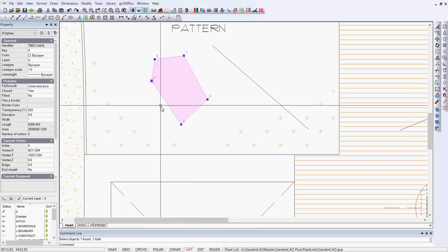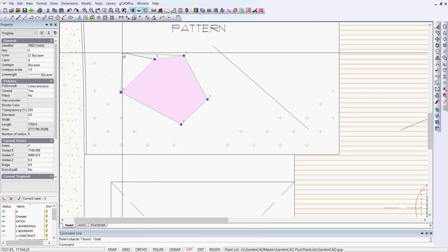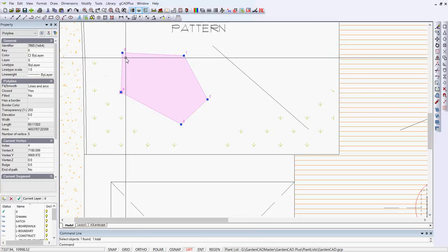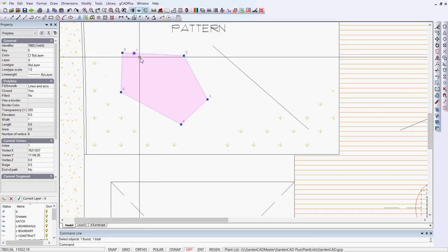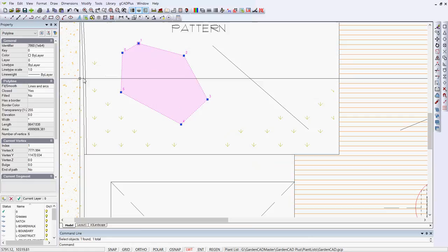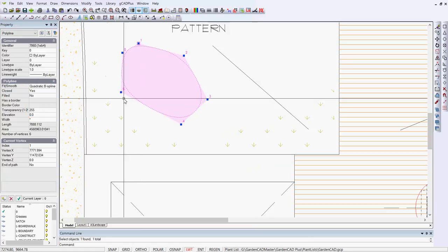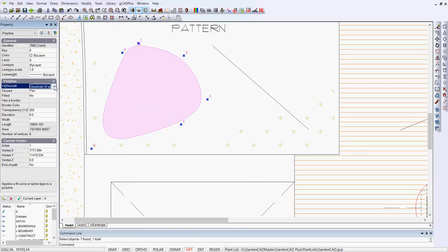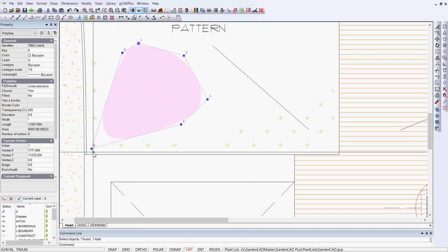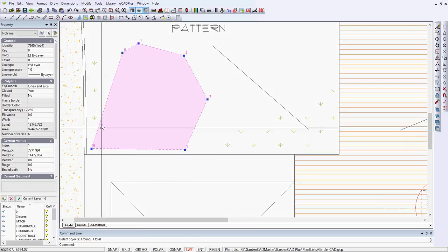Because this is a polyline that's hatched, and you see it's associative, so I can move my polyline around. I could add some extra vertices if I wanted to, as I've just done. So can you see I get a really, really nice shape? I could, if I wanted to, do some smooth curving. But can you see, actually I'll take that off because that's really a silly example, but what I can do is move my hatching like so.